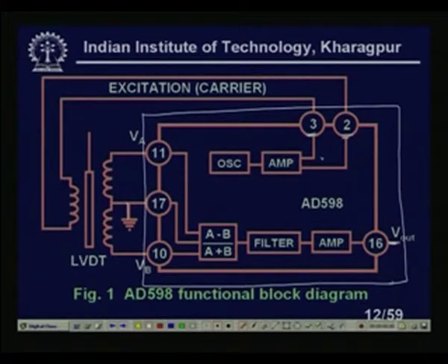Okay, to have a stable oscillation, what they do in the case of LVDT is first generate a triangular wave. Then with signal processing, they convert the triangular wave to an approximate sine wave, because a triangular wave can be converted to a sine wave. Then it is fed to the amplifier, and it is feeding the primary of the LVDT. Clear?